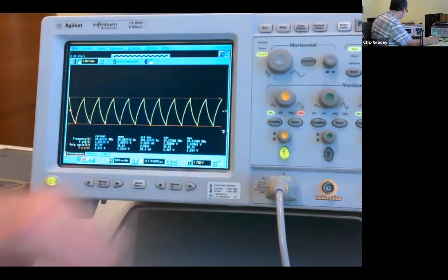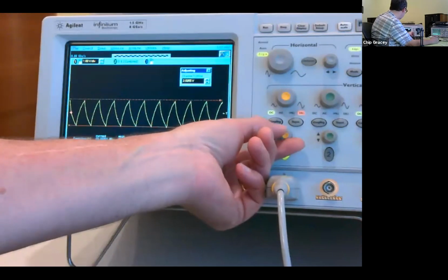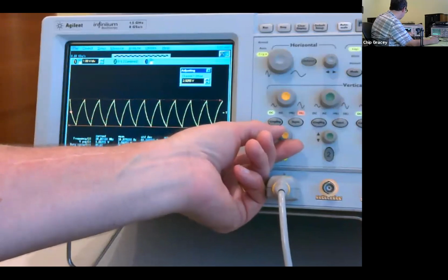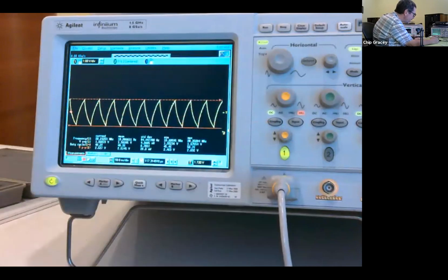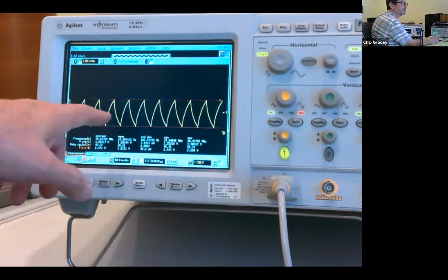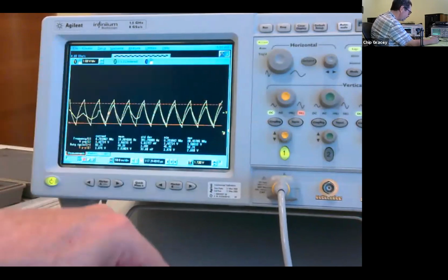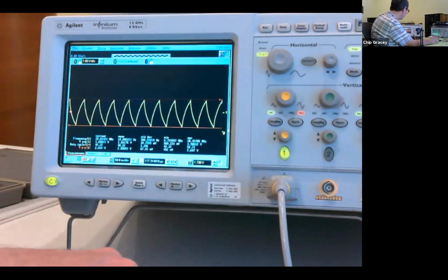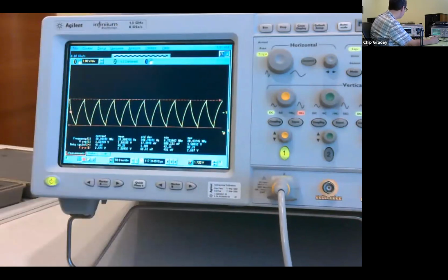It's driving high, low. And let's see, where's the ground at? The ground is right here. We're at 1 volt per division. There's ground. So it's not getting all the way to the edge because it's driving through like a 600 ohm resistor, and then there's some internal loading capacitance which is slowing it down. That was there for the crystal. If we had a crystal connected across this, you would see a nice sine wave here, like on XI. But because it's just open loop now, we're just seeing the driver outputting into an RC circuit.